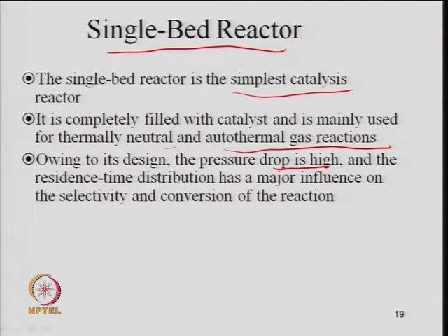Owing to its design, the pressure drop is high. So, as I said, it is a kind of packed bed reactor, right? So, if your particles are fine, very small powder type particles, then the pressure drop will be excessive, right? So, energy loss will be there. And the residence time distribution has a major influence on the selectivity and conversion. So, RTD becomes very important. We need to look at the residence time distribution, cold flow conditions, and flow visualization.